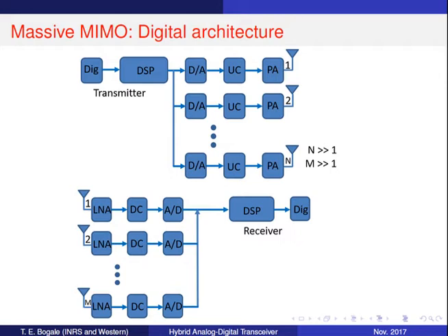This system is motivated to boost the channel capacity. To achieve this capacity boost, however, the separation between two antennas may need to be at least λ/2. Thus, when we deploy a massive MIMO system at low carrier frequency bands, the antenna array size would be extremely large.